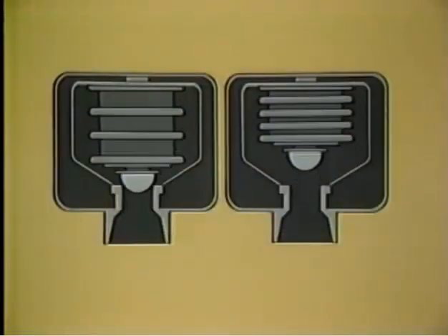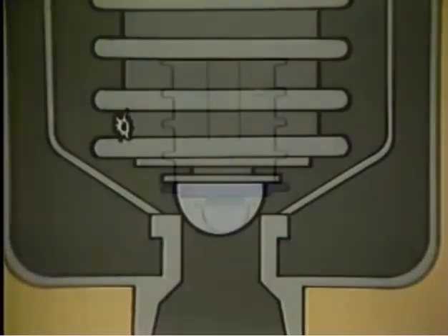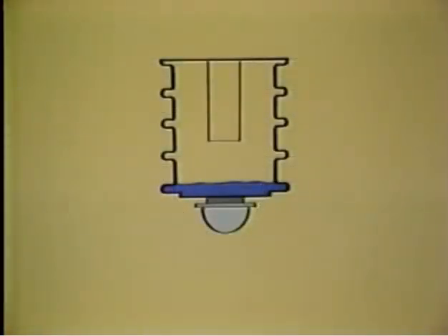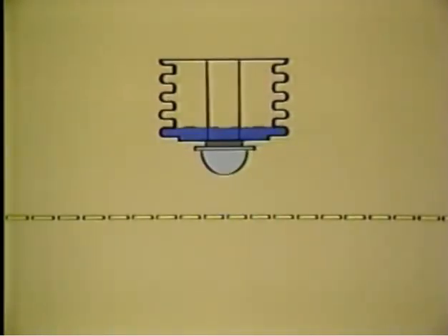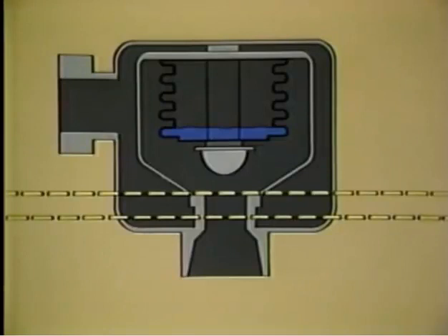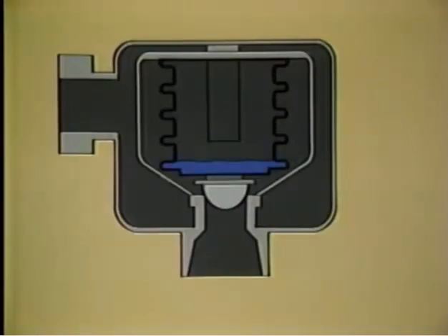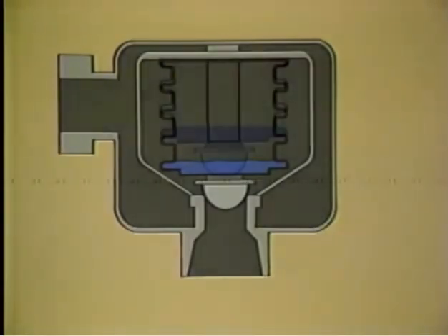There are two methods of constructing a bellows trap, which determine, among other things, how the trap will fail, open or closed. In both methods, the liquid charge is added and then a vacuum is drawn in the bellows, compressing it to an internal stop. Only water is used as the bellows charge of the trap which will fail closed, and the valve is positioned to seat just short of the bellows free length. If the bellows ruptures, it returns toward its free length and the trap is closed.